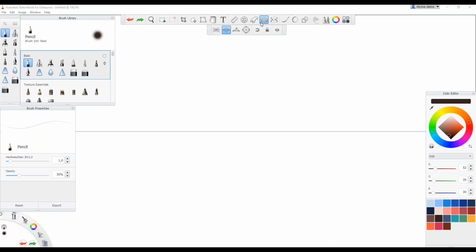If I drop that down, you can see there's 1-point mode, which, if anybody knows perspective, is 1-point perspective, then 2-point, and the differences in there. Depending on what you want to draw, you would choose appropriately. I'm just going to do my 1-point, and if I move my cursor, you can see there's a whole bunch of dotted lines, and it sticks to the 1-point perspective understanding that all lines join at that central point.